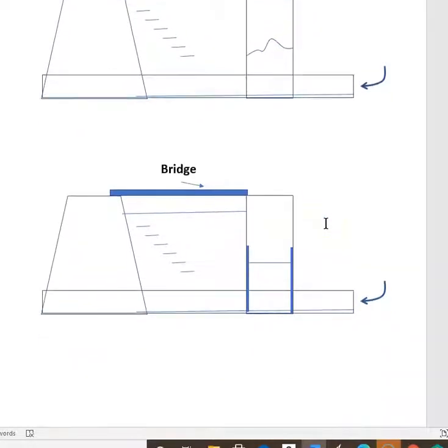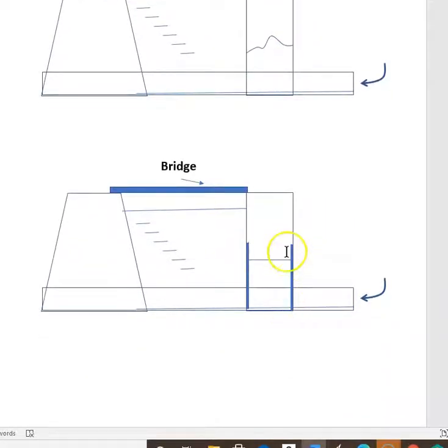And now in this design, where they have gates, you could control the flow. You could lift this up halfway and then let the water come in to whatever the amount you want, and then you lift it up here, and then the water would go nicely. Your pressure head is here. You're not going to get large, uncontrolled flow volume at the end.